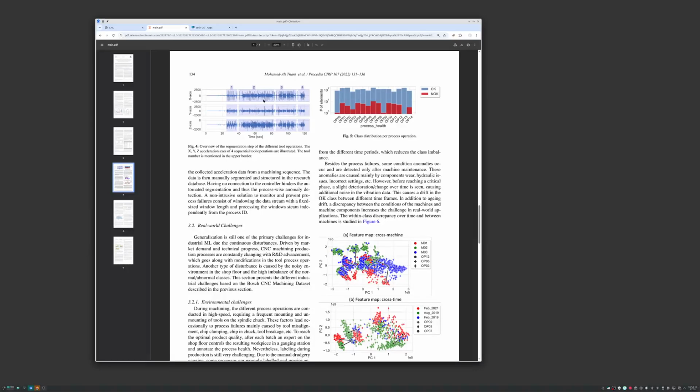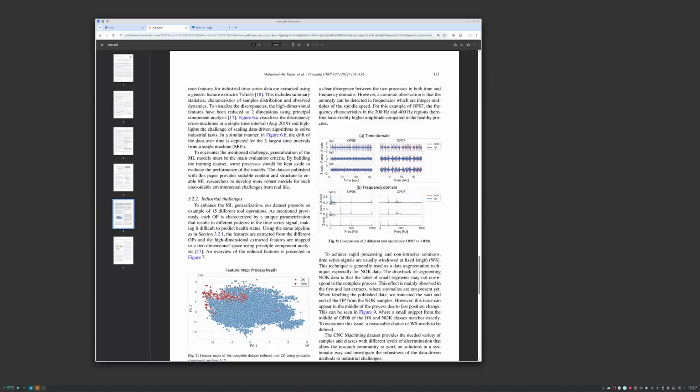As you might expect, what you end up with is typical style vibration data. The real challenge is that when you look at this in the time domain, you really don't see very much. And so the secret is to move from the time domain to the frequency domain. So perform a Fourier transform on the data. And then you will see clear spikes at points where there is a particular prominent frequency in the vibration data.